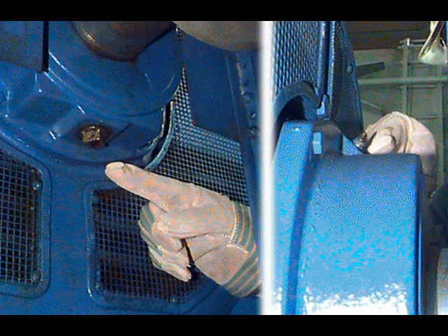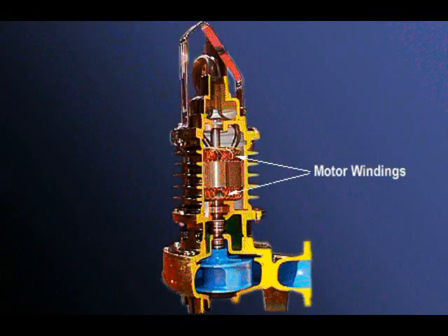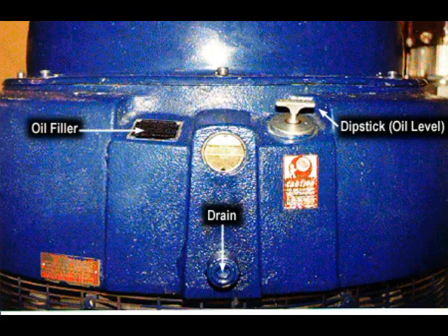These bearings may be greased or oil lubricated. This picture shows a typical grease fitting on a motor. Certain parts of the motor, such as the windings, will be quickly ruined if they are exposed to lubricant. These are oil lubrication parts of a motor bearing. On large motors, there may be three: the filler, the level, and the drain.